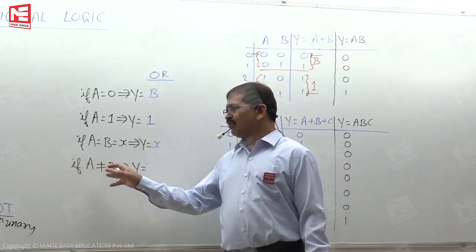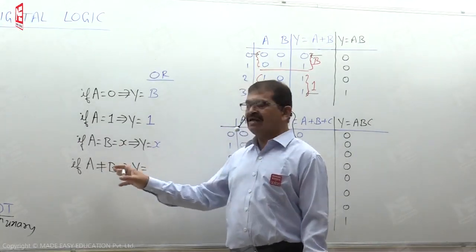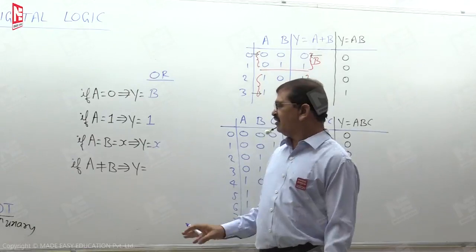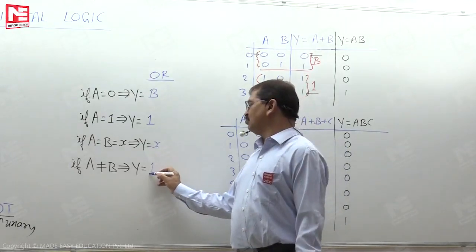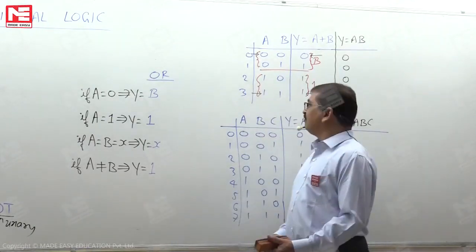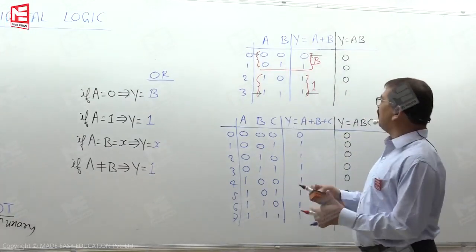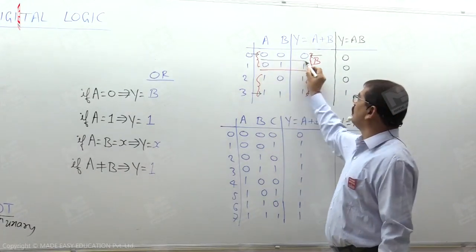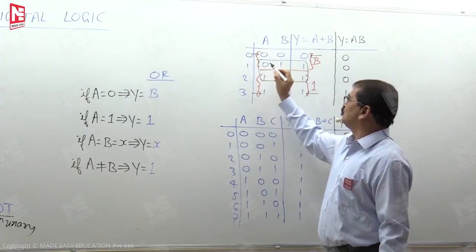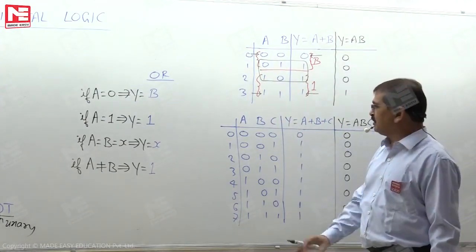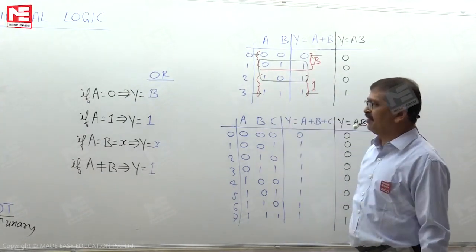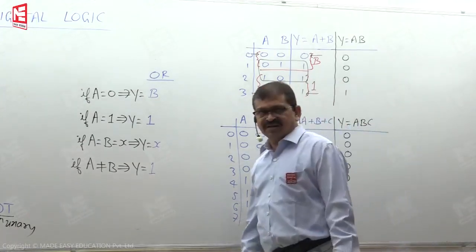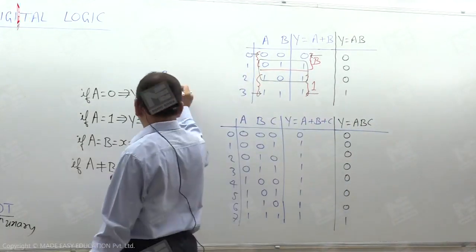So whenever this condition is true, one of the inputs is guaranteed to be 1 for the OR gate. Hence, the output is 1. Alternatively, we can read it from the middle two rows of the truth table: whenever A and B are not the same, the output is 1.